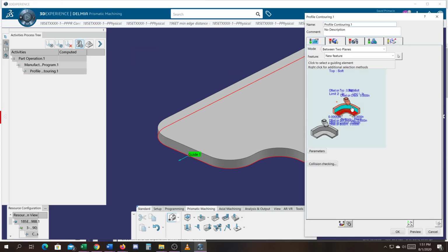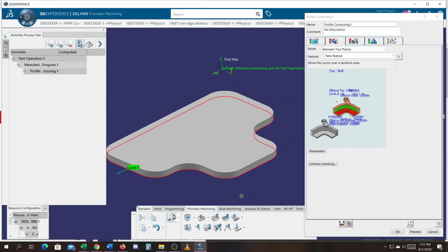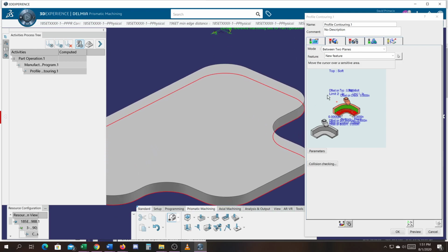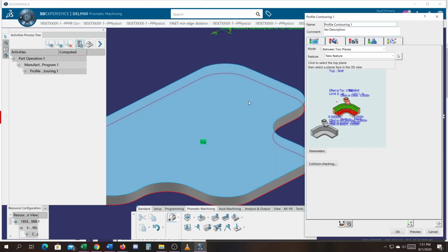And this whole side face becomes green. Again, that's kind of confusing because it looks like I'm going to grab the side face here, but you don't. You grab that bottom edge that would represent where that sketch was. All right, then I think the other part will be pretty simple. It's like drilling the holes. I'm going to select the top surface here and grab this surface here.